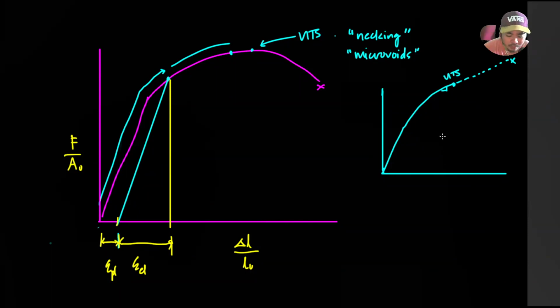Okay? So, siguro narinig nyo na rin to, no? So, while we're on the topic of UTS, pagka nagko-compute tayo ng true stress, so naalala nyo pa yung true stress to. So if this is sigma, let's call the true stress as sigma T, no, and the engineering stress as sigma E, tapos epsilon T ang true strain, and epsilon E ang engineering strain. Dapat pala E yung ginamit ko dito. Sige, para mas consistent tayo.